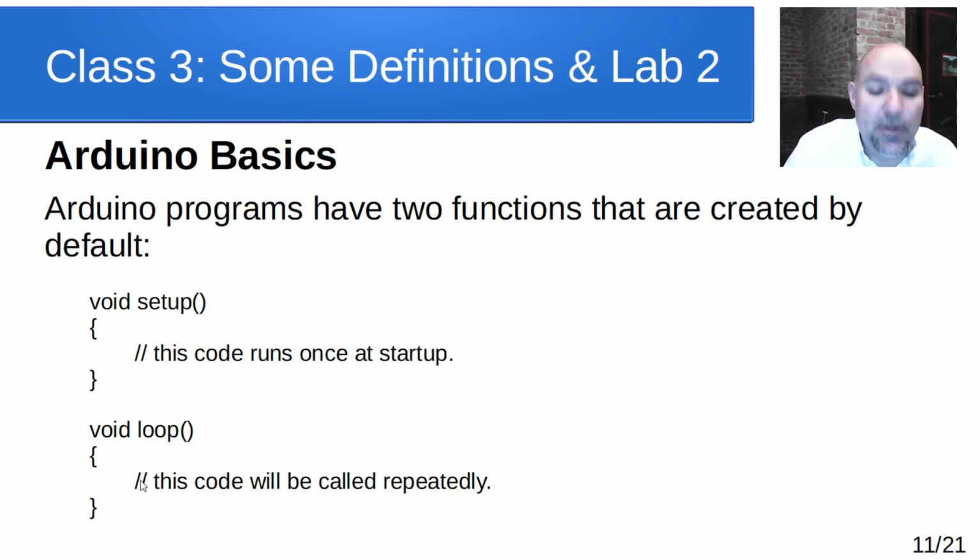So we can write code in here. We don't have to put a while loop inside of here. We just write some code, and we can know that it's going to run it, and then it's going to call that function again, and again, and again, as long as the microcontroller is powered on. So we power it up, it runs setup once, and then it starts repeatedly calling loop. You think of it like a repeated action goes in here. Generally setup kinds of things go in the setup, which makes sense, so it's called setup. And things you want to repeatedly do go into loop.